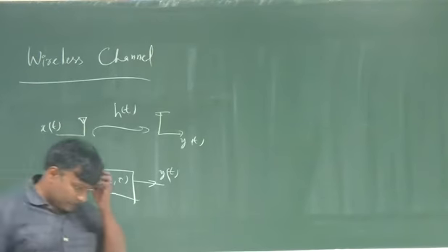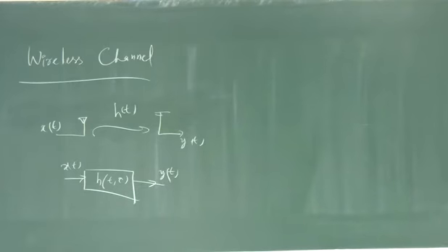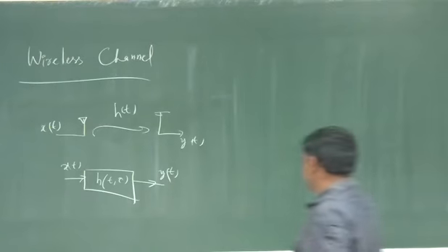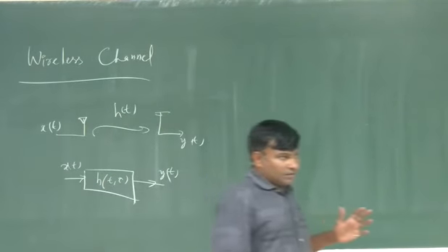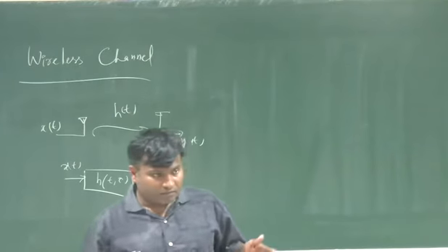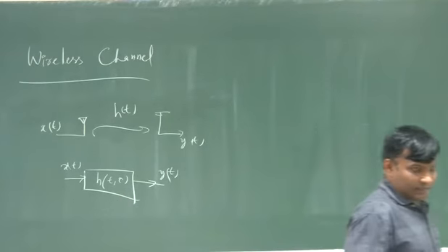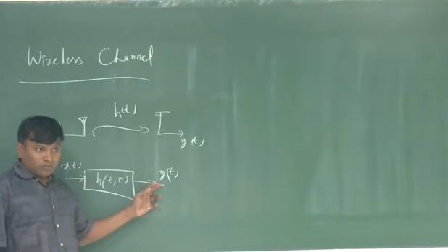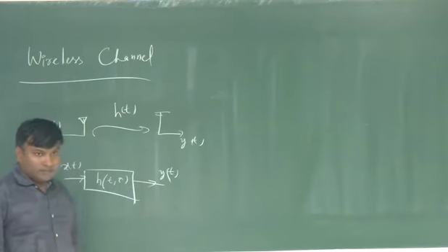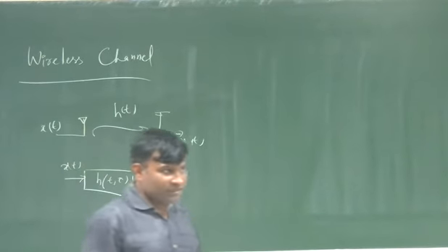We'll come to this in a moment. Channel response could be a time varying channel response. We model it as a linear system, possibly with a time varying channel impulse response. What does it mean? Let's say we measure the channel impulse response. Let's say the channel is varying slowly. Clock of, let us say, 1 millisecond. Send in a unit impulse and you measure the response at the output. You get, let us say, h of tau. That is the channel impulse response as a function of tau.